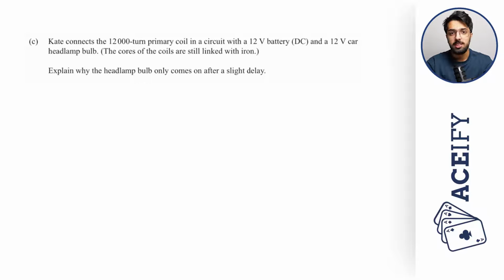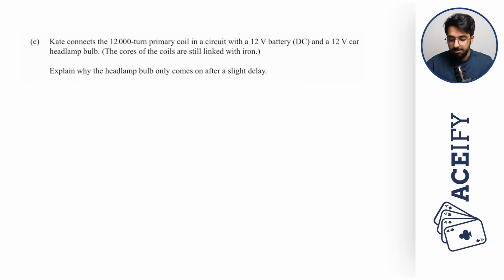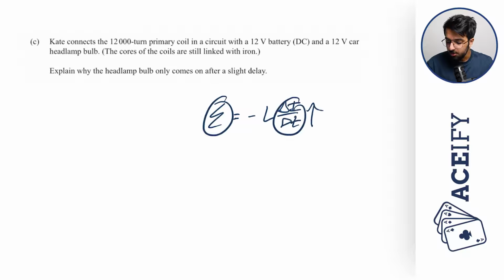Alright, so when we turn the car on, aka that's when the power supply is going to be turned on, the current is going to start to rise from 0, okay, because obviously when the car is off, the current is 0, and so therefore there's going to be a high rate of change of current. Therefore, due to this high rate of change of current, we know that the EMF induced in our inductor is equal to negative L change in current all over change in time, and so therefore if there's a high rate of change of current, the back EMF is also going to be high.